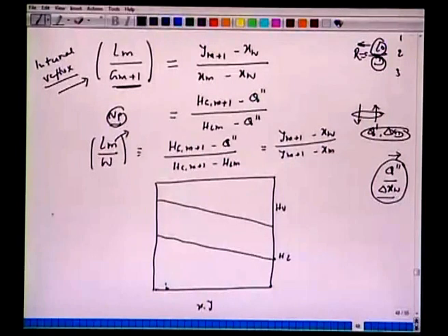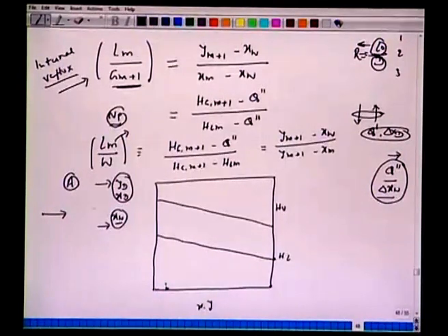We have the distillation, feed enters here, top product rich in A. So, we have y_D or x_D very large, say 90%, 95%, and the bottom product is lean in the more volatile component. So, we have this x_W very small. So, if A is the more volatile component, then this bottom product stream will be rich in B and lean in A. So, we are here, and let us mark this point.